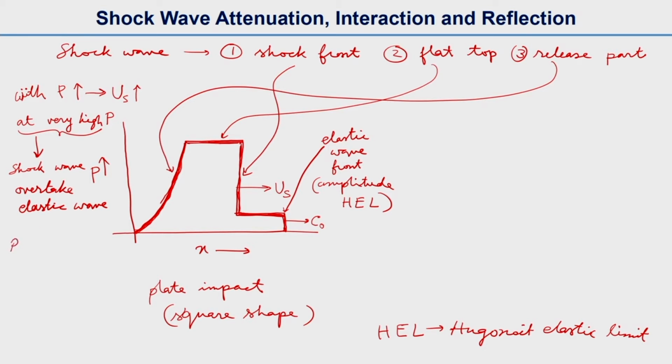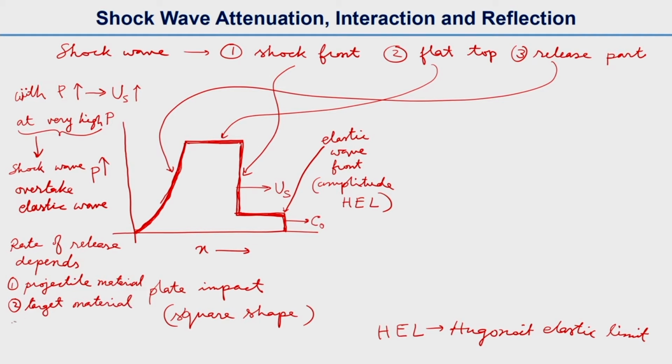So the rate of that release, how fast it will decrease to zero pressure, depends on the properties of the projectile material and target material, and also the travel distance of the shock pulse.